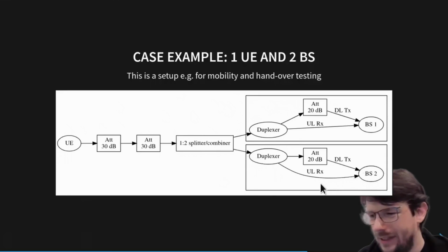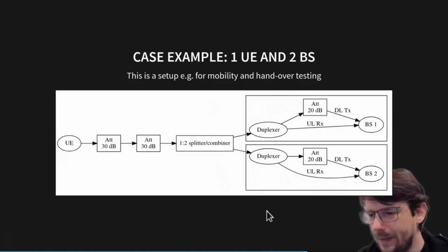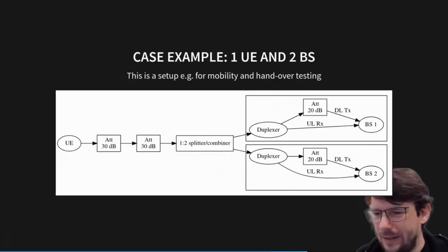artificially the receive level here, we could add a digital step attenuator or a rotary step attenuator in this path here or in this path here or even here or here. Then we can make one cell level lower than the other cell, and at that point, once the hysteresis values and whatever is configured for cell reselection would make the change between those 2 cells. I can also see the measurement reports as they adjust and so on. So that's an example in that direction.